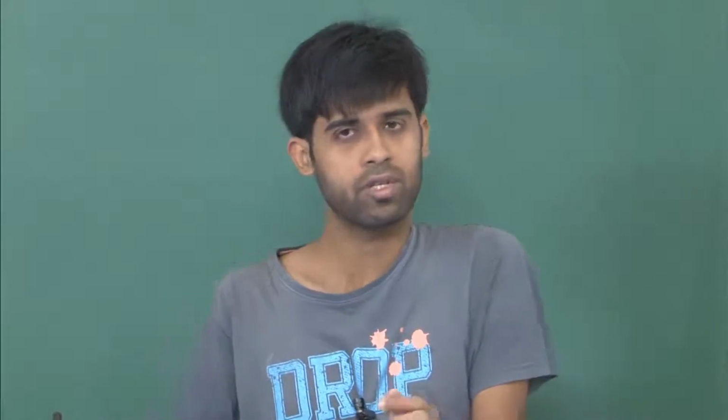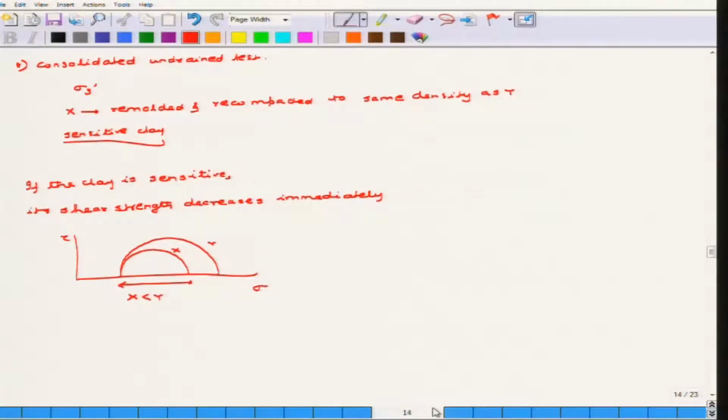Similarly, if the sample is subject to a greater pre-consolidation pressure, then obviously the sample will behave in an over consolidated manner, and if it is a drained test, then its void ratio is going to increase. So in this case the strength is going to reduce. So depending on all these cases, for the same sample tested under different stress conditions, you can find out how to physically interpret the behavior and strength of the samples. Now, we will move to the third problem.